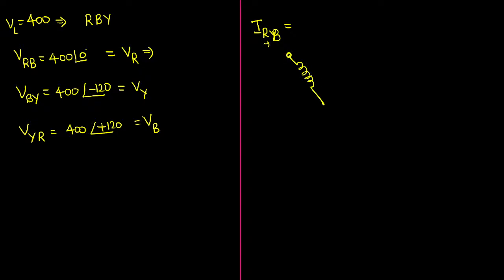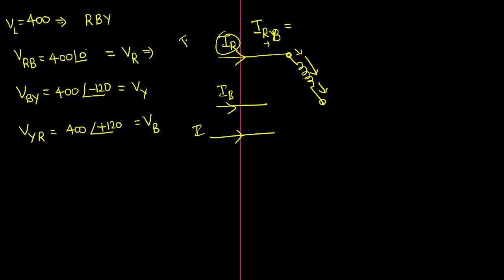See, there I am going from this point to this point. In between these two points we are having a phase line. So this current is called phase current. Then which one is called a line current? Line current is that which is coming from phase R, phase B, phase Y. It is opposite to star connection. Like in star connection, IR, IY, IB is called phase current, but in delta connection, that is called line current. Both are not the same.